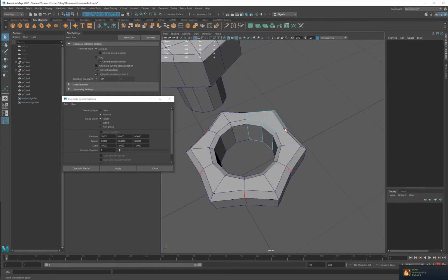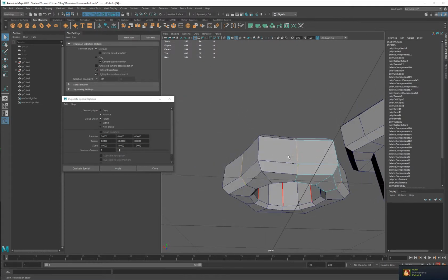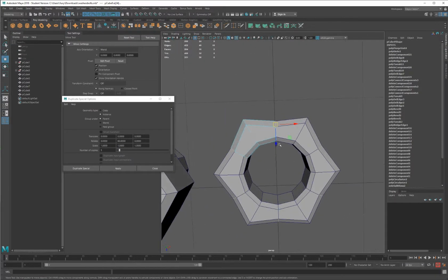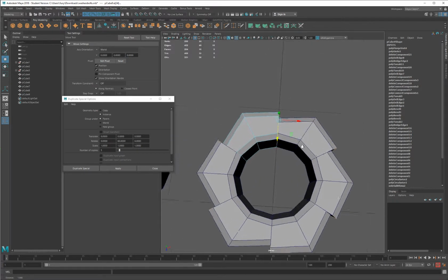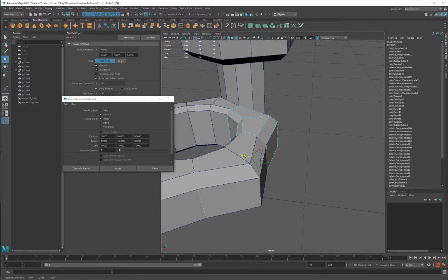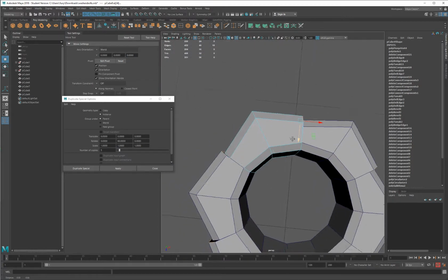So now, if I go into edit mode on any one of these, they're actually all linked together. So now I can grab this couple of edges, 1, 2, 3. I'm going to leave the bottom and the other ones intact. Going to go into my move tool. Going to hold V to snap the vertices. Drag this one up and snap it to there. And that did not. Oh, let me move the pivot of it first because we want to be along with that vert right there. Then snap it to there.